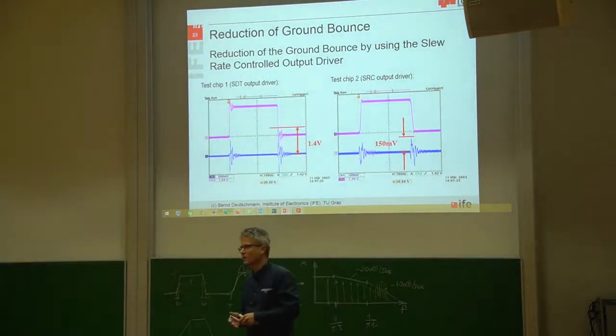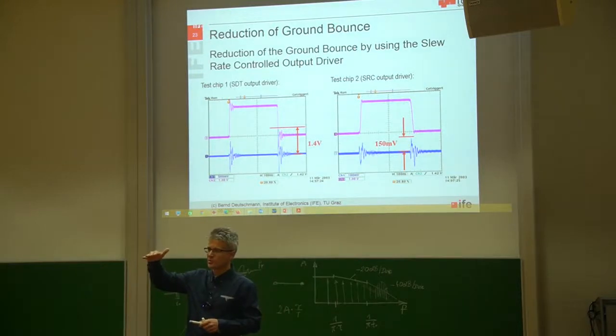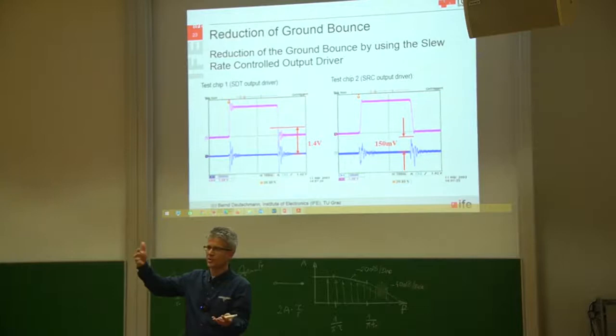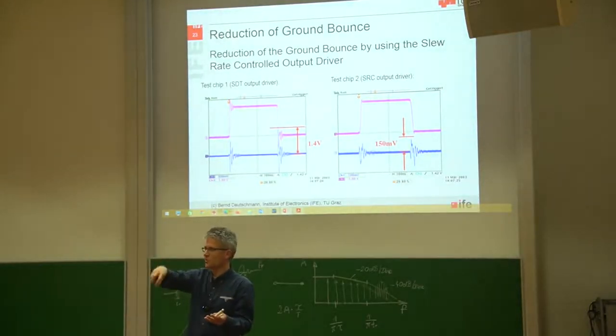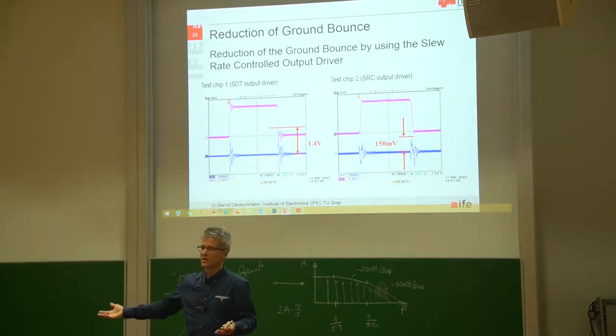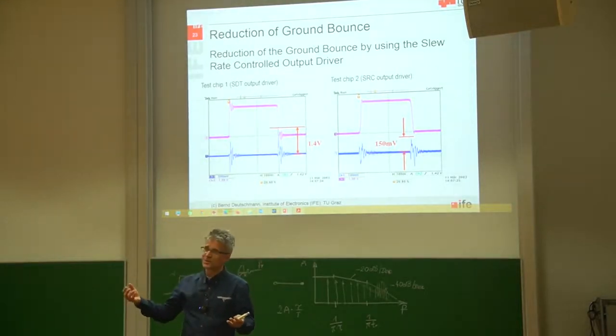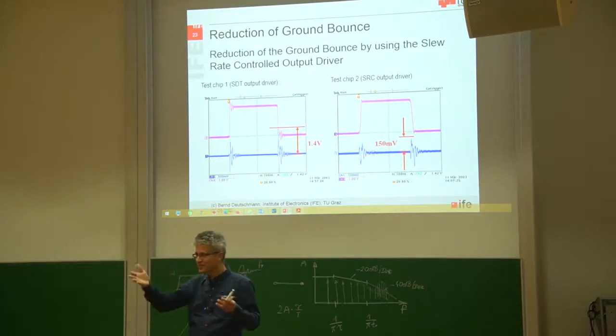So this is the voltage potential shift between the ground potential of the substrate and the ground potential of the printed circuit board. When your crowbar current and the dynamic switching current is flowing out of the substrate via the bond wire to the ground pin, and then to the ground of the printed circuit board, there is always a voltage drop along the parasitic inductance of the bond wire.